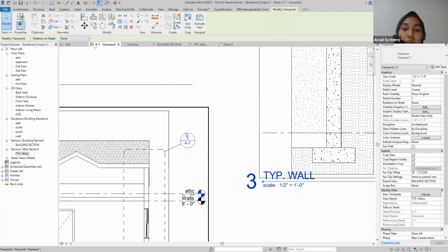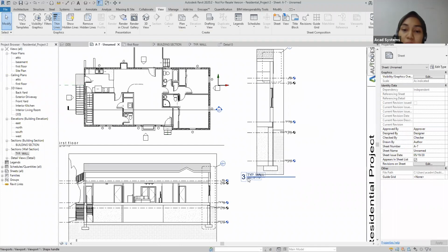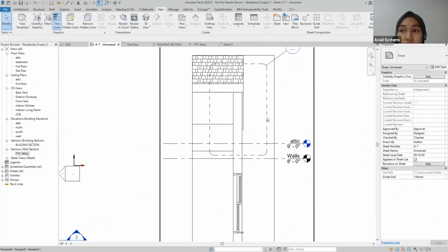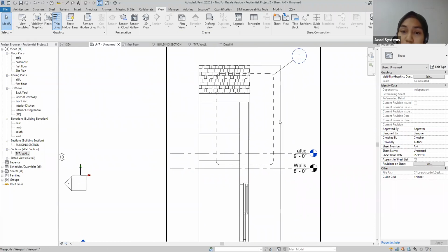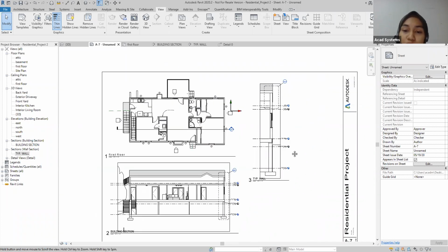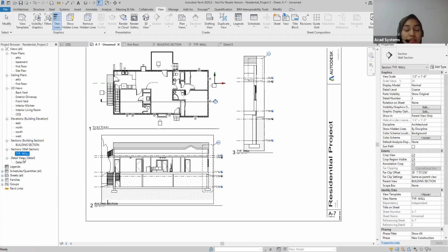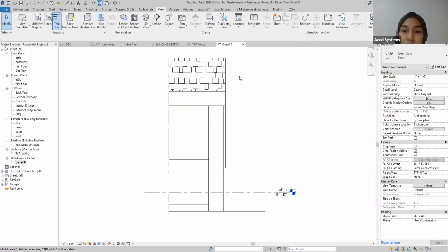And you can see that the empty details here are already refilled by number 3 because it is referring to this number 3. And in this number 3, I created another callout, but this one is a detail view of this. It's still empty over here, if you see. So I'm going to drag the newly made one, and if you see here at the details view, the latest one that we made falls under the details view, and it automatically gives you the name detail 0 here.